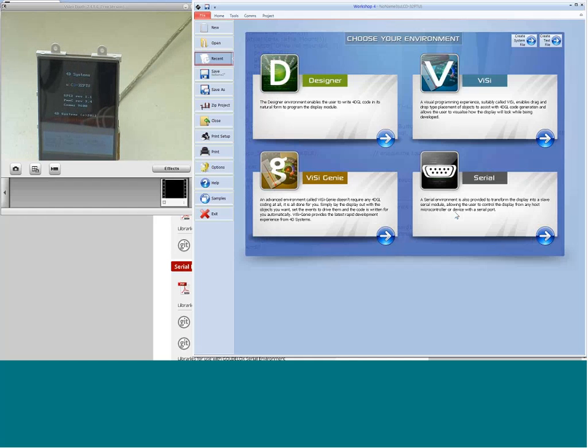Okay, there is one question. Is it possible to debug a program in the Workshop IDE? I mean, it is possible if you have problems compiling. But in real time, like debugging, it's not possible. But you can just connect the display with the programming cable to your workshop, and you can throw up the code you have. You don't have to disconnect it every time.